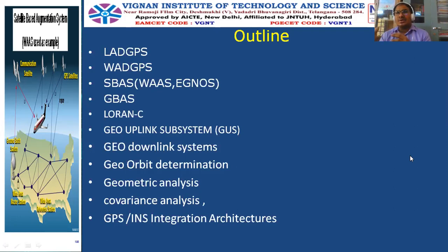Now the known location and the calculated location are compared, and if there is any mismatch, then we conclude that the calculated location is erroneous, due to some induced errors. That may be due to ionospheric error, clock error, or tropospheric error.